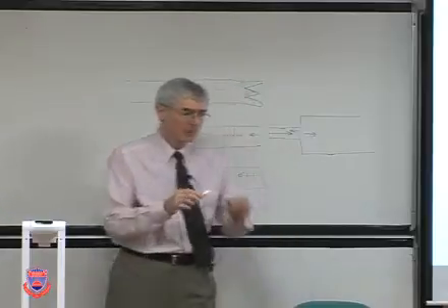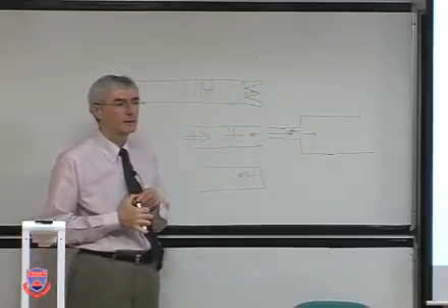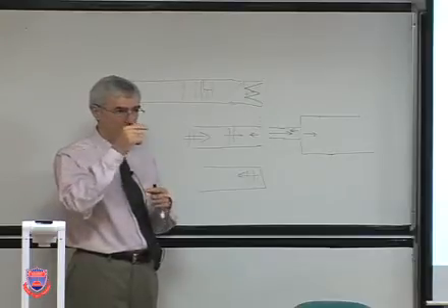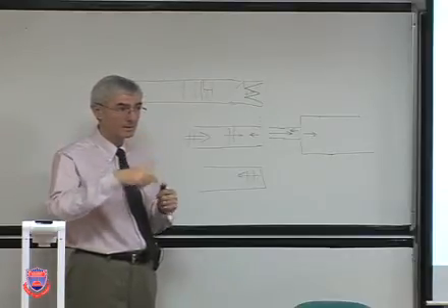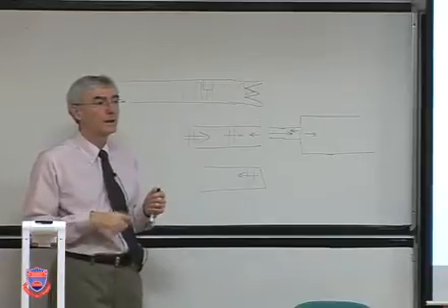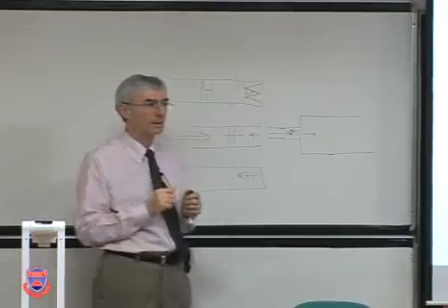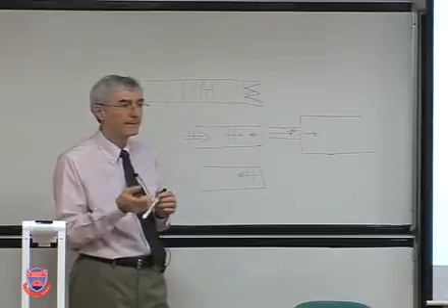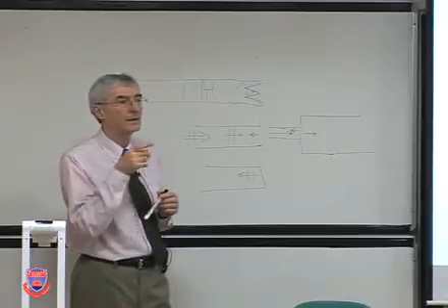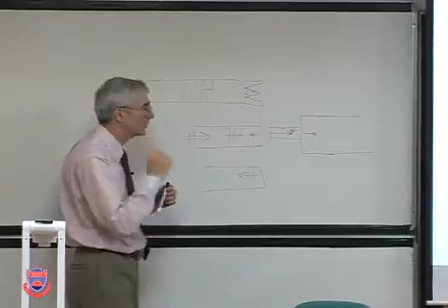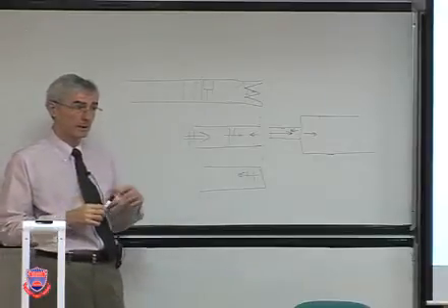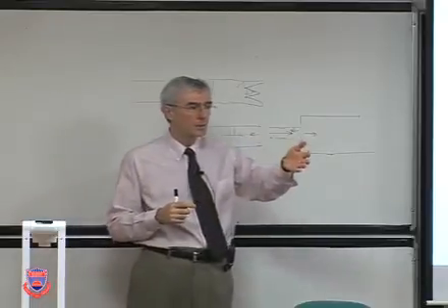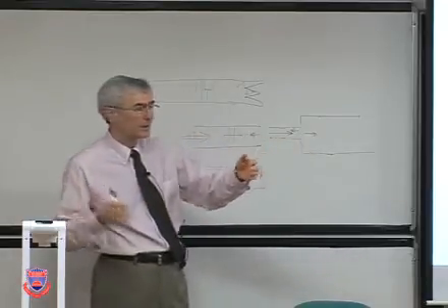What is the basic mechanism of that? What's impedance? It's rho C, the specific. Yes. In general, it's pressure over particle velocity. Pressure divided by particle velocity is the impedance. And for a plane wave, that's equal to rho C. That becomes the characteristic impedance.